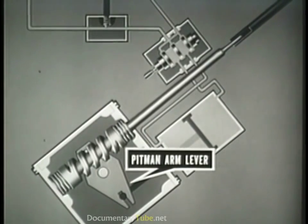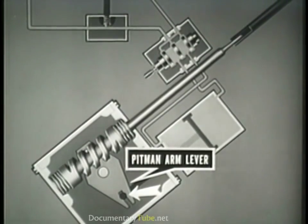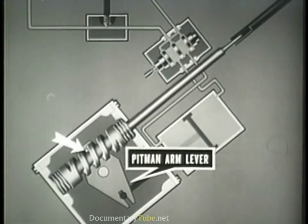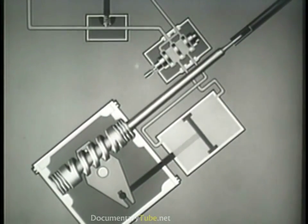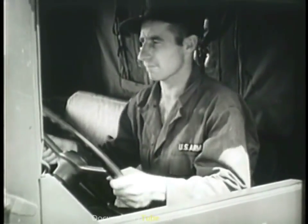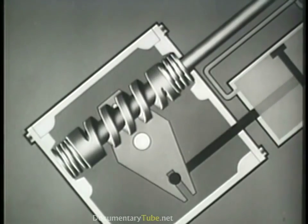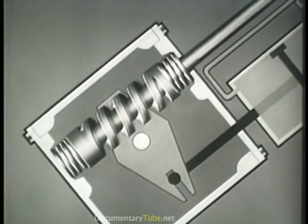The pitman arm lever, which actuates the pitman arm, has one end fastened to the piston rod, the other in mesh with a groove in the steering cam. When the steering shaft is turned, it requires a greater effort to turn the pitman arm shaft and lever than to compress the springs at either end of the cam. This is so because the pitman arm shaft and lever are connected to the front wheels. This action causes a cam spring to be compressed, allowing the cam to move up or down, depending on the direction that the steering wheel is turned.